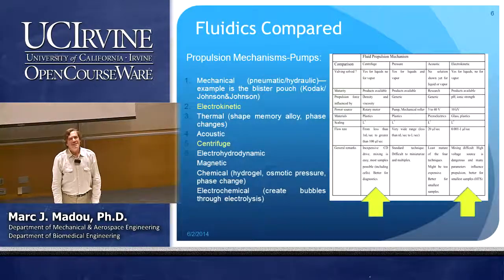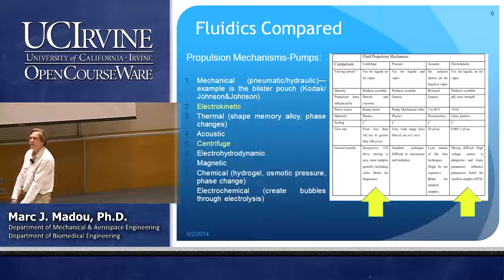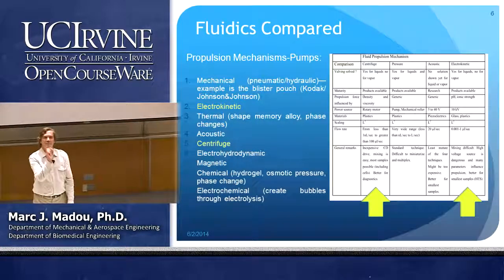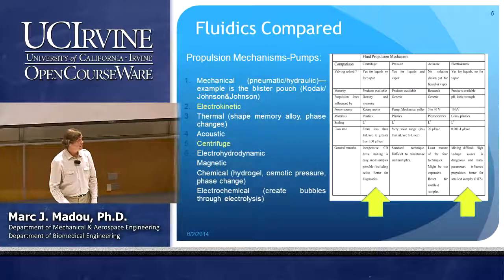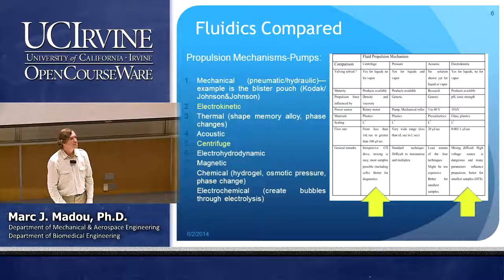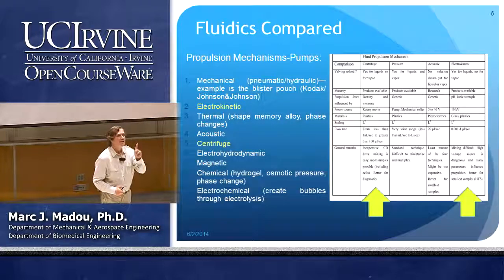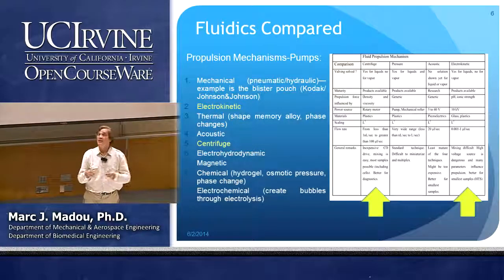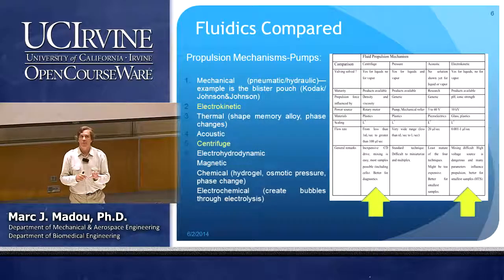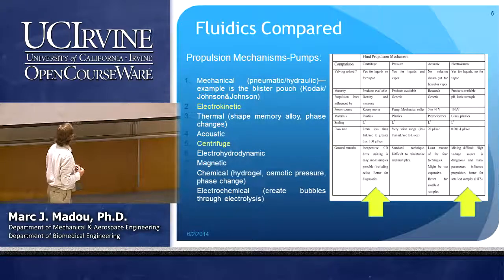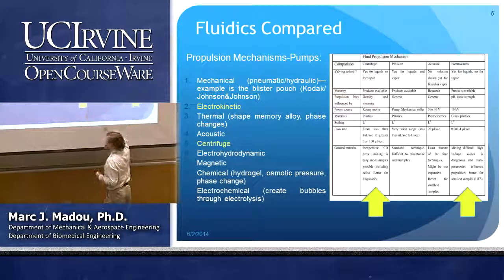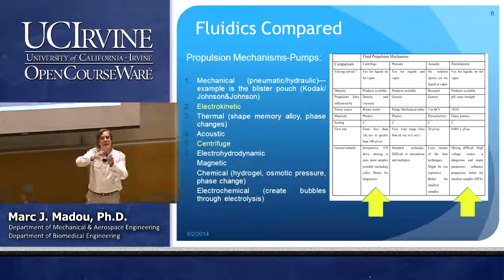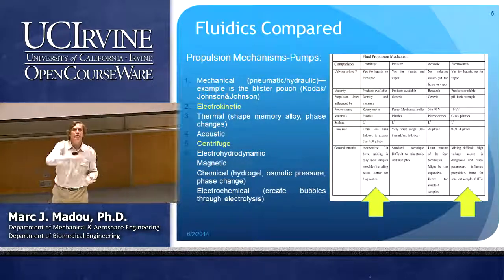So what that means is it's very difficult to miniaturize that technology, right? If I want to pump liquid into, let's say, a 100 micrometer capillary, I will have to apply a lot of pressure. That is a big negative on using pumps in biomedical equipment, especially if you want to miniaturize it. So you can put a big cross there. What I've written is that it scales as L to the 3rd, because it's a volume scaling. It scales with the volume of the liquid you're pushing.